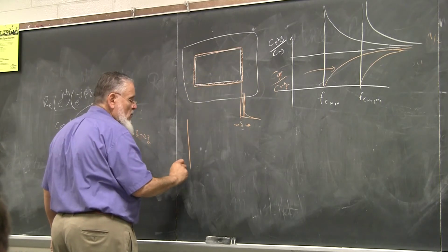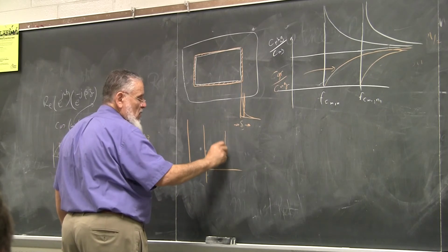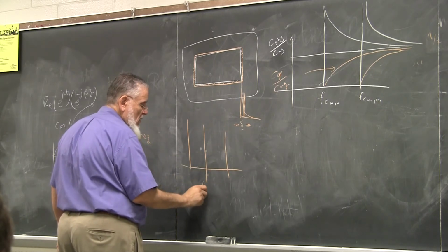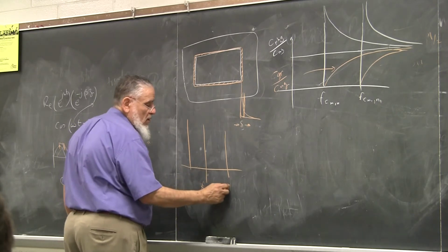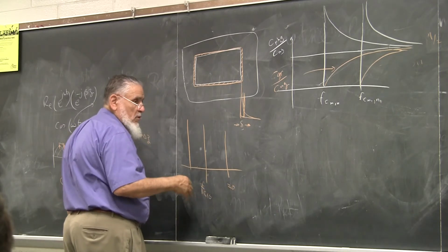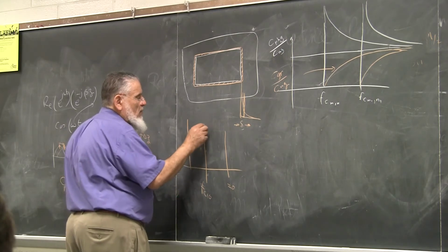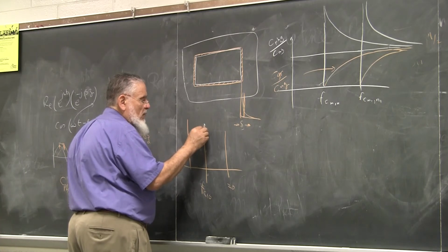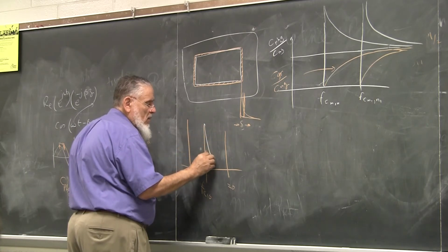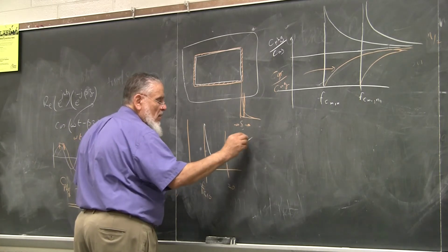and if you do that for the TE10 mode, you will discover here's the 10 mode, right? This one here is FC10, and if we said the next one will be the 20, because we do A is greater than 2B, right? We discovered that the attenuation almost goes to infinity right at the cutoff, and eventually dips down and starts to rise again, right?